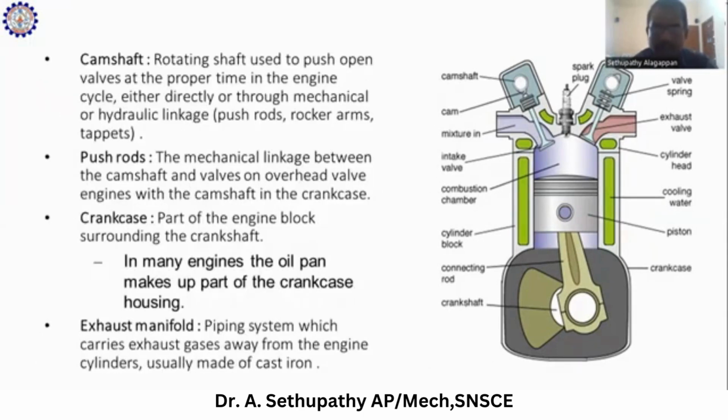Then the camshaft, a rotating element. It is connected with the valves. The valve opening and closing time depends on the camshaft rotation. Then push rods, the mechanical linkage between the camshaft and valves on overhead valve engines with the camshaft in the crankcase. So the push rods operate the valves. Then the crankcase, the part of the engine block surrounding the crankshaft, is called the crankcase.